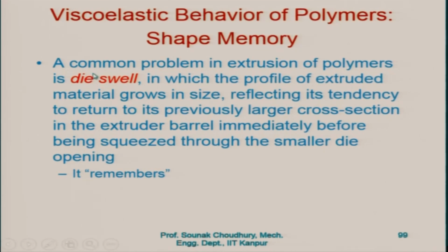A common problem in extrusion of polymers is the die swell, in which the profile of extruded material grows in size, reflecting its tendency to return to its previously larger cross section in the extruder barrel immediately before being squeezed through the smaller die opening.